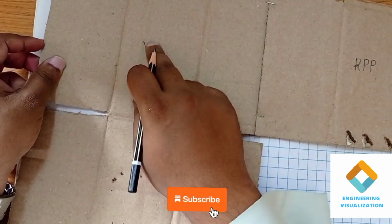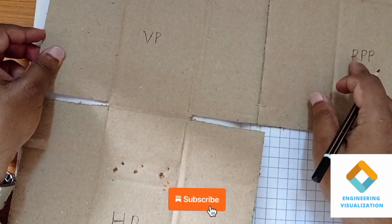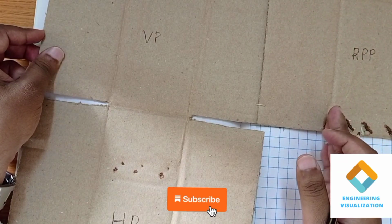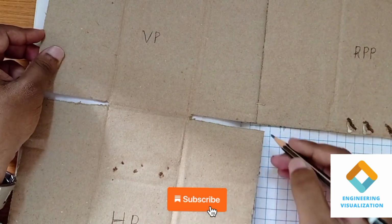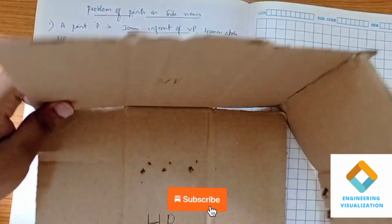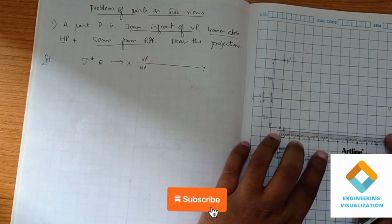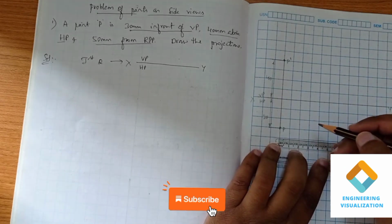So front view, top view, and this front view is connected with the side view. For this RPP we will be drawing another x1 y1 line at a distance of 50 mm. To draw this side view with the top view, we will be using a 45-degree angle line. Just follow the procedure. From this projection point we have to consider a distance of 50 mm, that is 5 boxes.